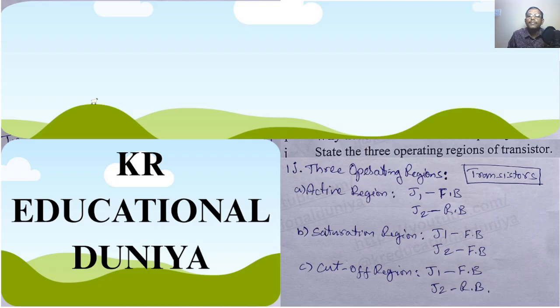Next question. State the three operating regions of a transistor. This also comes under the transistors unit or BJT unit. The three operating regions are the active region, saturation region and cutoff region. Active region means junction 1 is forward biased and junction 2 is reverse biased. Saturation region means both the junctions are forward biased. Cutoff region means both the junctions are reverse biased. Okay, cutoff region, both the junctions are reverse biased.